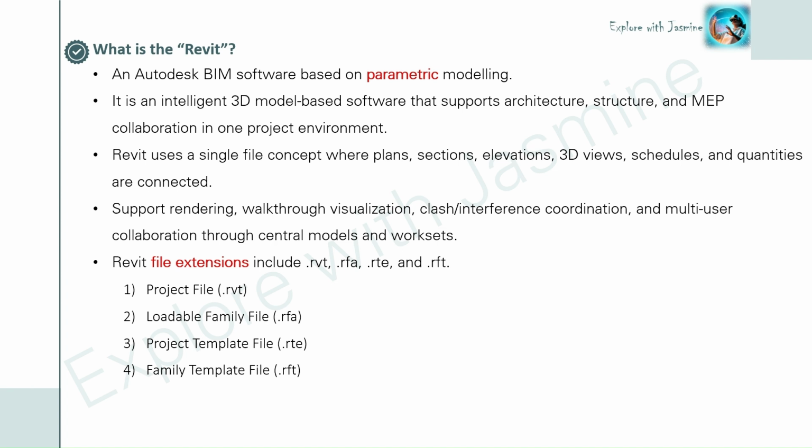Lastly, Revit uses several common file extensions: RVT for project files, RFA for loadable family files, RTE for project template files, and RFT for family template files.